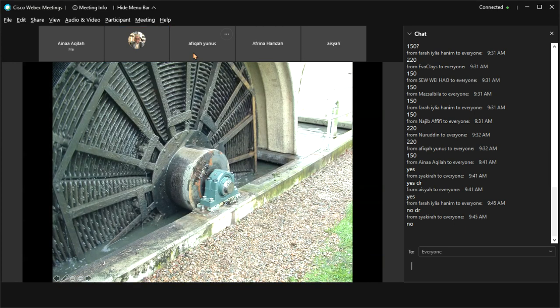One of the problems with this is that the shaft here is exposed to the water. There are many metal parts being exposed to the water. And this media will get heavier and heavier, and because of the weight of the media, the shaft can break. And you see this corrode. The corrosion will also cause the motor or the rotator to have problems rotating.